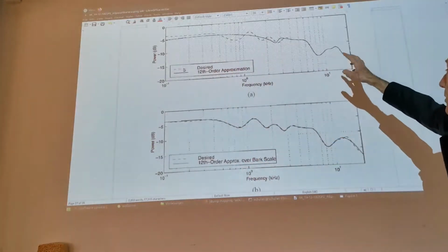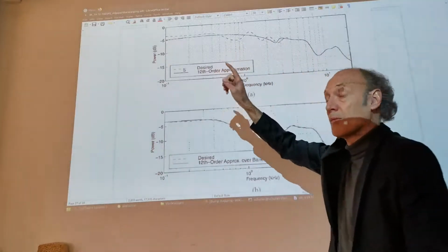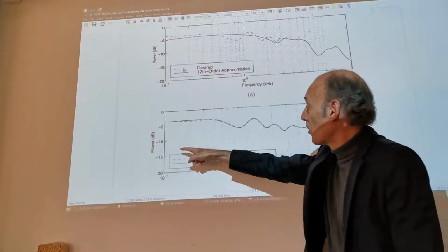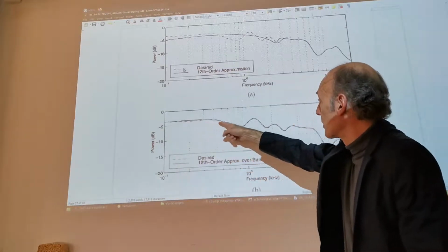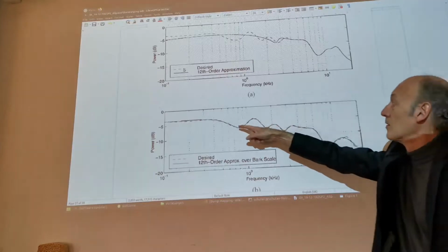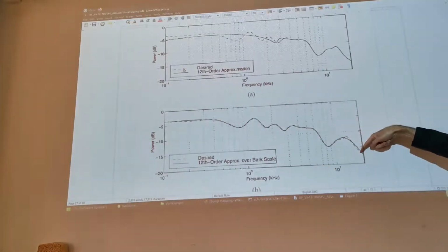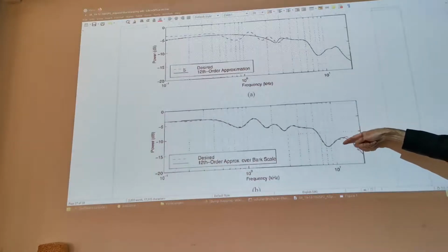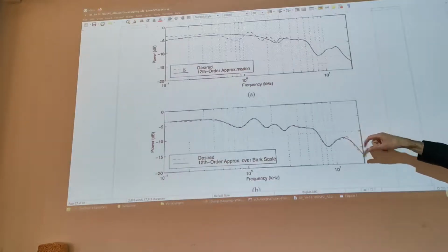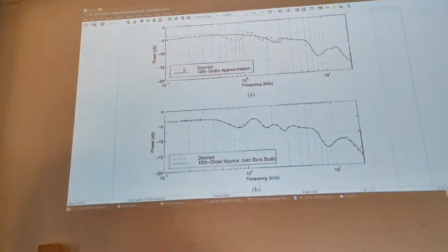And so this filter is not doing such a good job here in the low frequency range. But when you apply warping, frequency warping, then here you get this solid line. You can see it matches much better the region of low frequencies, but then at the cost of some detail here at the very high end. Right. So usually this is actually much closer to what we want.